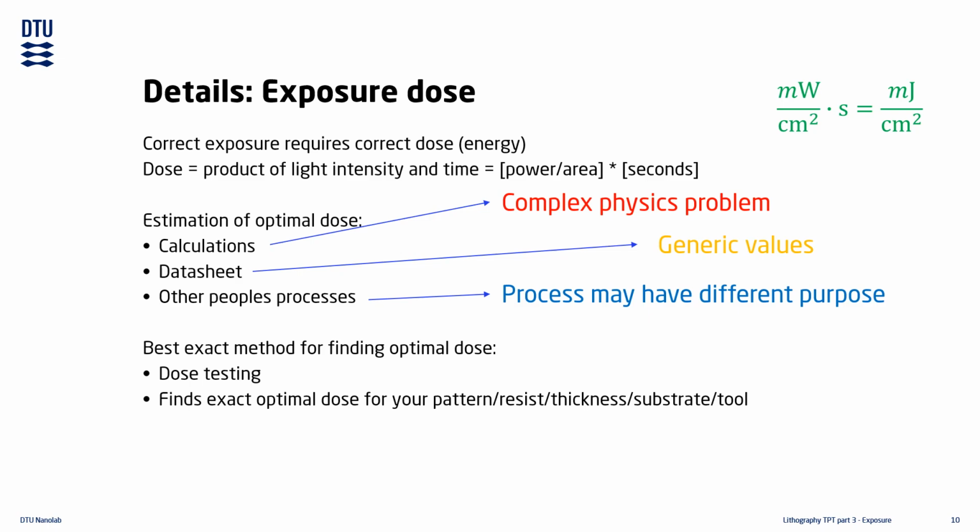After going through all the work finding your optimal dose, you unfortunately also have to sometimes repeat that work. Ideally, everything inside the cleanroom would be constant, but that is just not the case. Tool performance can change over time, or tools can outright break. Ambient humidity changes with the seasons, which can impact the resists as well as certain tools.